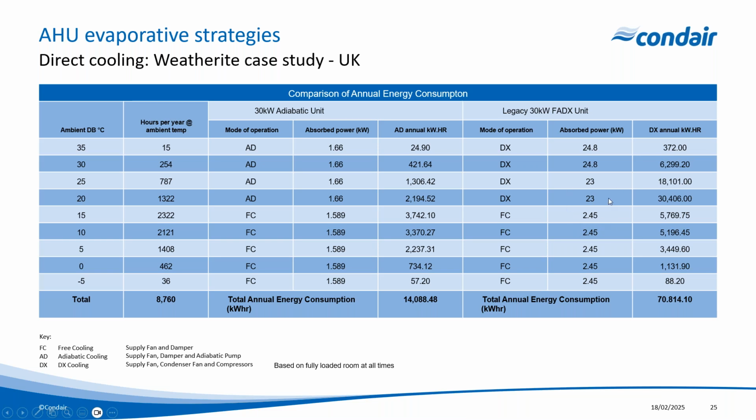Now, if you compare that to the legacy DX cooling unit, going from free cooling to DX cooling mode, you can see a significant increase here. So we're going from 2.45 kilowatts all the way up to 23 kilowatts. So a huge difference there on the DX cooling unit.